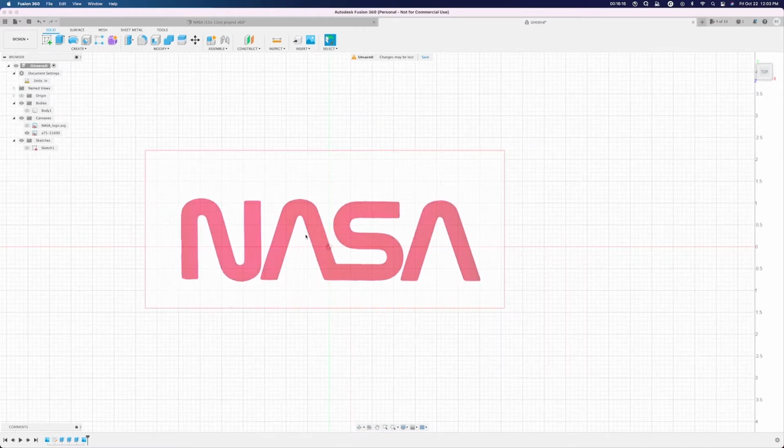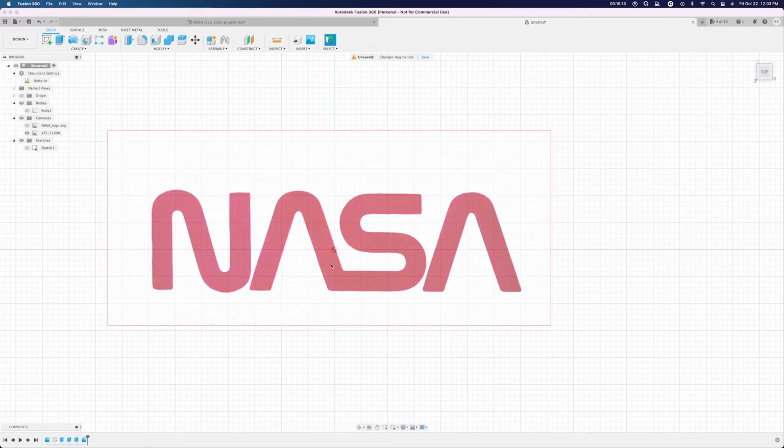Now, to start the sketch, I want to note that there are 3 separate bodies, meaning that we'll first need to sketch the N, then the AS, and then the A, which are 3 unique sketches, but they will be done at the very exact same time. In order to do that, we'll be using different tools for this process. We will be using the Control Point Spline tool and the Line tool. The Spline Curve tool allows us to draw around the curved corners, and the Line tool allows us to draw straight lines on straight paths.